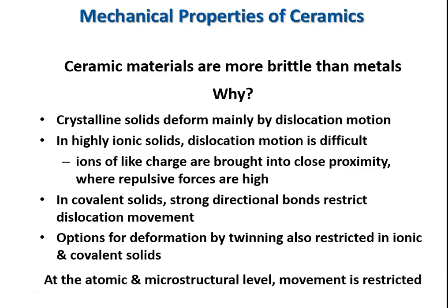And again, when the forces are that high, it may be easier to form a surface with the air, which means fracture. And the same with strong covalent bonds. Even though you're only moving a few of them right at the edge of the dislocation, nonetheless, it may be so hard to move those few bonds that it's easier to create a surface and fracture the material. So it's truly the strength of those bonds and the inability to move a dislocation that makes these materials so brittle.